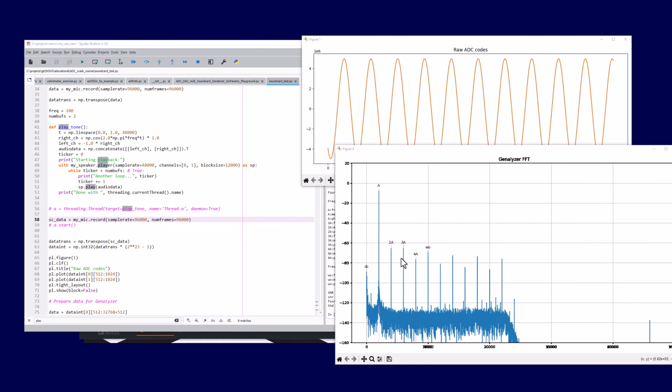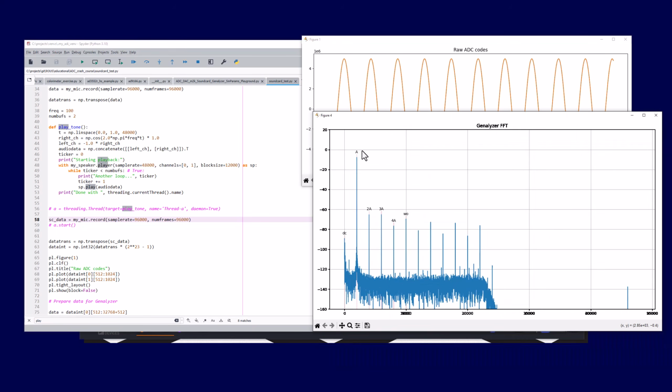points here or there. So when I stopped recording and reran this test again, here I get exactly what I'm expecting. So yeah, in the FFT here, I see my fundamental, I see my second and third harmonic, and they're right about the same place they were with Scopy. So yeah, it appears that Scopy is not doing such a bad job here.